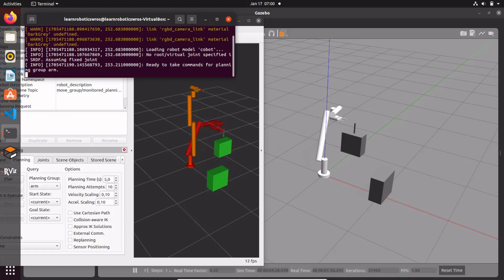Here you are. This is a complete and functioning pick and place application simulated in Gazebo with ROS controllers, a position controller joint trajectory controller for the joint from the base link to the gripper connector, and for the gripper you are going to have an effort controllers joint position controller.